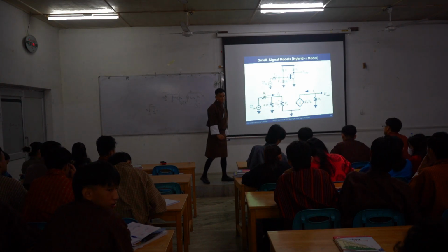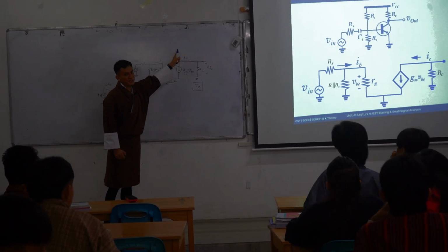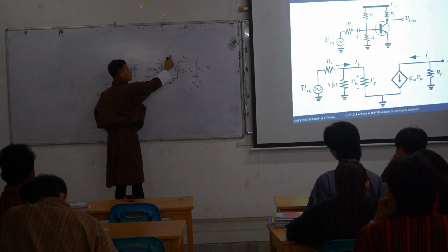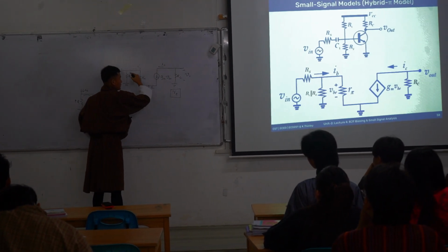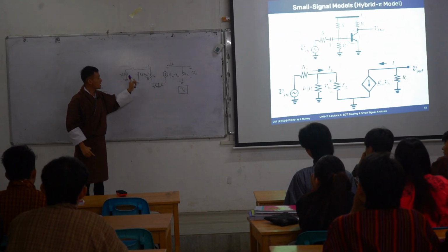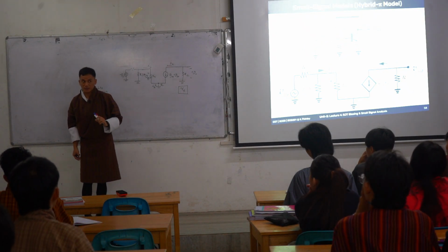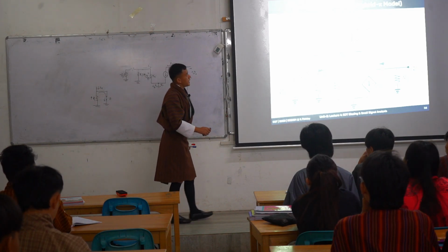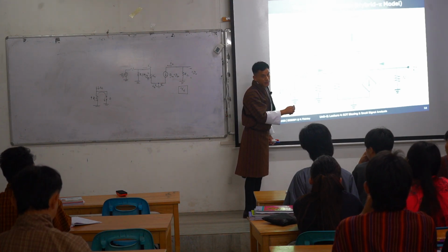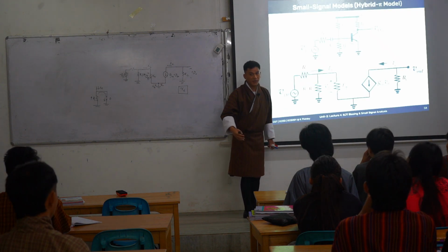So please remember how to represent this one in AC analysis. First and foremost, you need to remember this part. After remembering this part, you have to remember how, if there are some resistors at the input side, they are connected. For instance, during AC analysis, this will get grounded, this will get grounded. Because of this, R1, R2 and RS are parallel to each other.